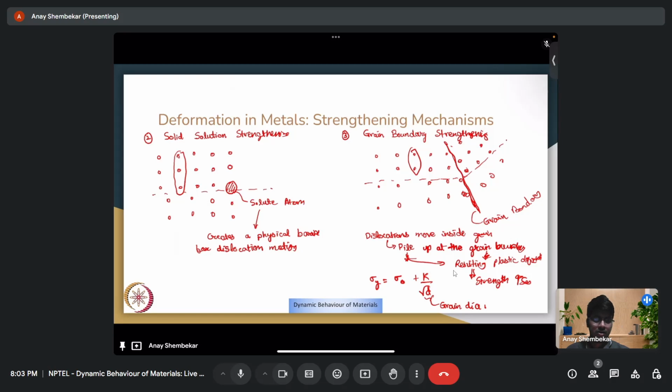It's like a lot of empirical relations. It's valid for a good number of observations, but we should not think that we can make the grain size indefinitely smaller, because that would add another sort of effects. That's an entirely different area of study in nanocrystalline materials.